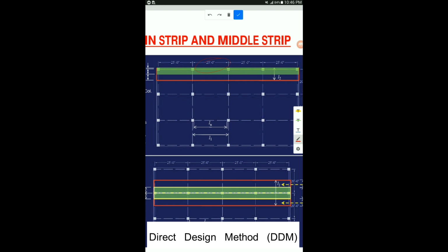In order to find that, you have to cut the center lines, because this rigid frame is running in x direction, so ultimately you have to cut these center lines in the building, the ones I showed here, like this one and like this one. So the distance from this to this will be the equivalent rigid frame width, which is quite clear from this example: it is 20 feet, because these are the span dimensions here.